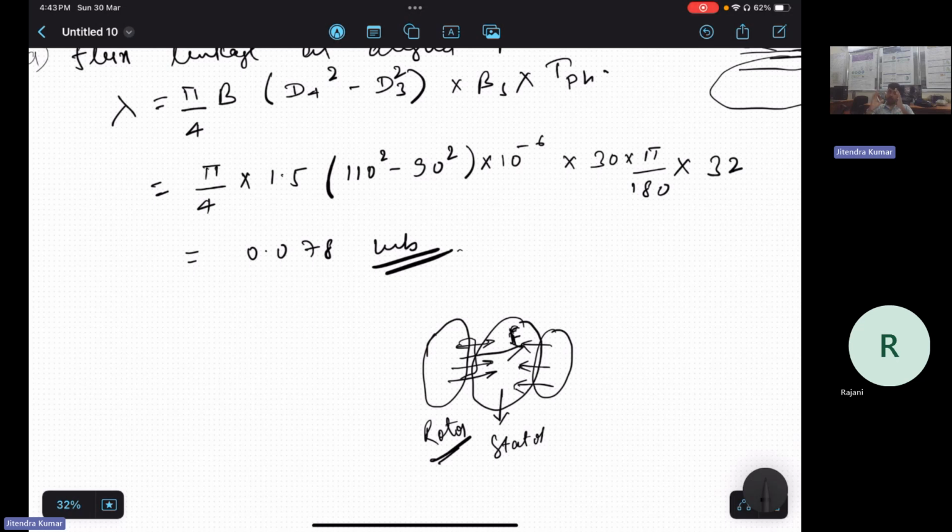That is why people placed one more rotor, so that the force is balanced. The amount of force created by the left-hand side rotor, the same amount should be created by the right-hand side. So the force should be maintained, and the issue of unbalanced pull should be mitigated.